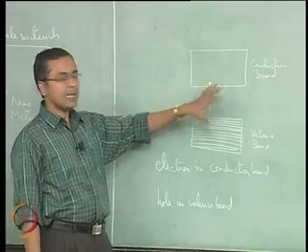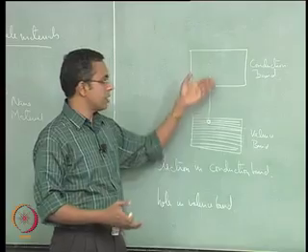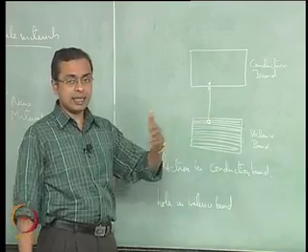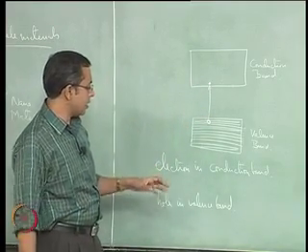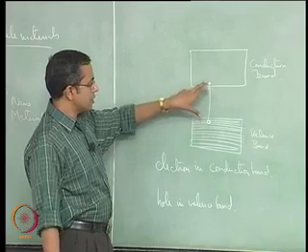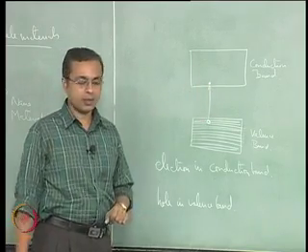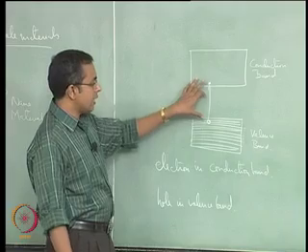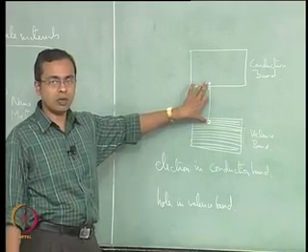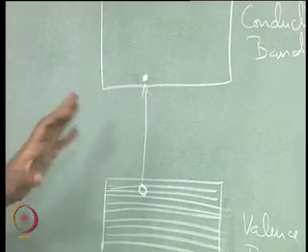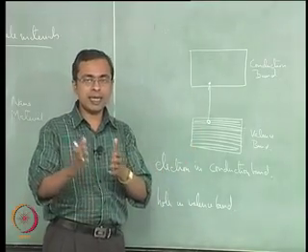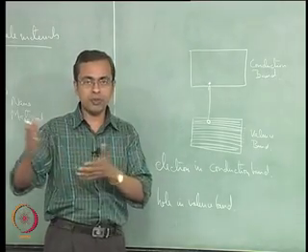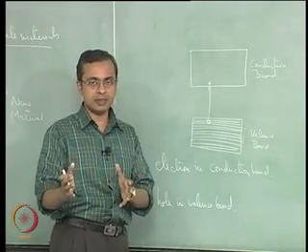Okay. So, when you talk of a band, you normally talk of it as, once the electron has gone there, it is free to run across the extent of the material. And that is how you talk of conductivity and so on. What I am telling you is that in that process, every time you do this, the electron and hole entities, which we have tended to talk of as independent entities, what I am trying to point out is they tend to have some force of attraction between them because they are oppositely charged, and as a result there is an attempt on their part to stay connected, to stay within a certain distance of each other, and so when they move, they keep maintaining this distance or staying within the limits of this distance. Okay.